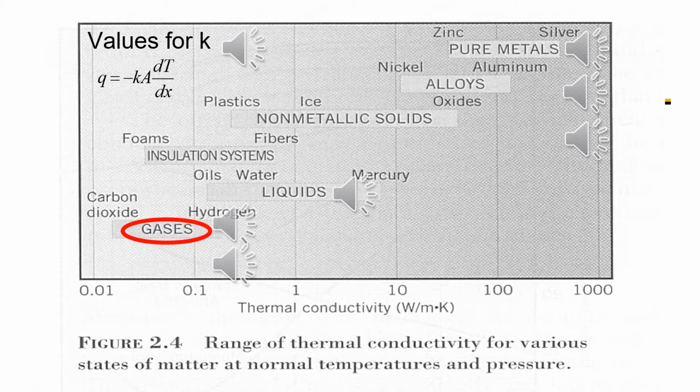In a gas, the molecules are far from each other, so the opportunity for them to bump against each other is less than for a liquid or solid, hence the conductivity, and hence the heat transfer rate, will be lower. For liquids and solids, the molecules are progressively closer together, resulting in faster heat transfer, and hence a higher thermal conductivity.